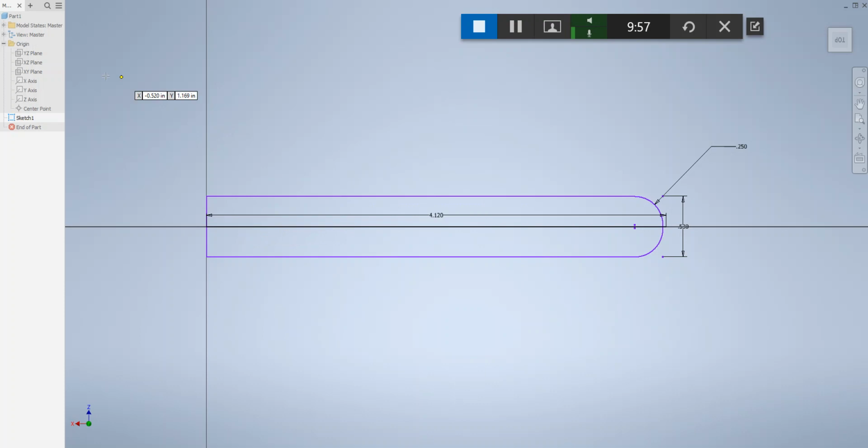We're drawing a 1-inch diameter circle, first of all, and it should be a little bit off the center line. So I'm going to be selecting a casual point above the center line, approximately this big. And now the computer is highlighting the diameter, and diameter is going to be 1, enter.